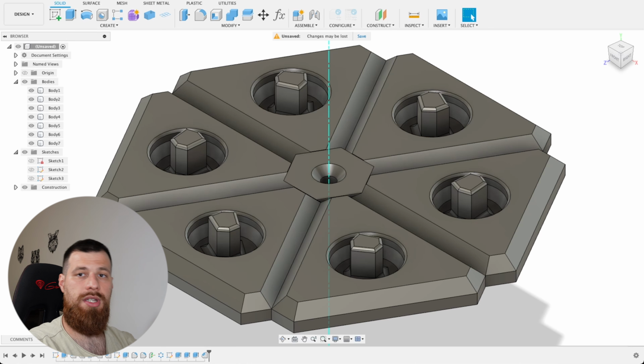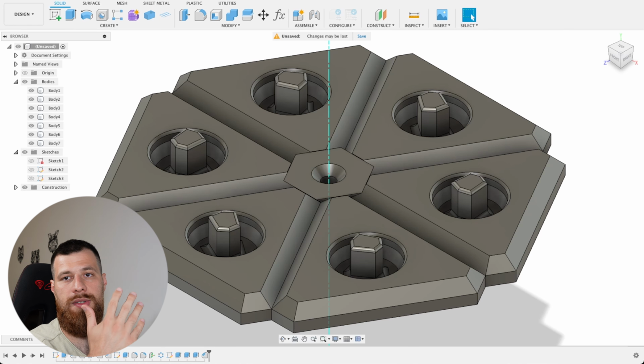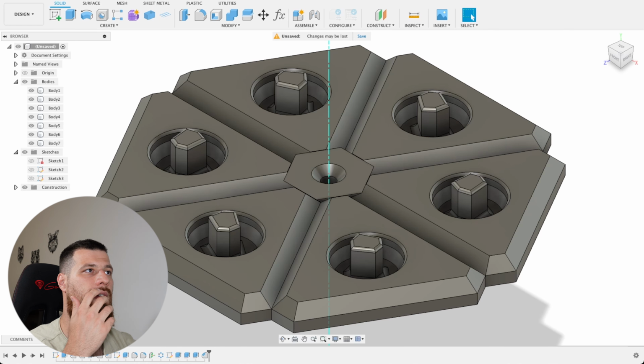Now, let's do a summary of what we've learned today. We've set up Fusion360 for parametric design, we defined some constraints from the beginning. Those constraints would be saved as parameters and then used in the design. Then we created dependable parameters, which are the parameters that have been created depending on previously defined parameters, which were constants.